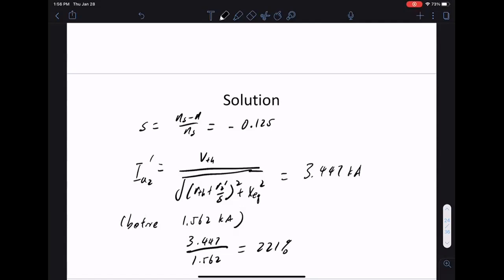With this kind of current going through, it's hard for the protection device to figure out: is this a normal part of connecting an induction generator to the grid, or is it a large current because of something else? That's why this large inrush current is not ideal for this operation.